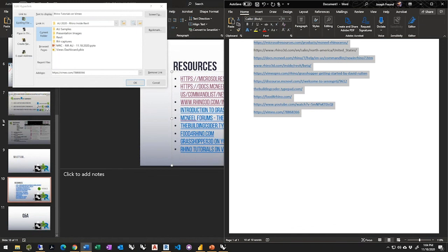There have been a couple that talk about the BIM 360. So BIM 360 is a hosting platform. If you open your BIM 360 model inside the Revit environment, you can continue working with Grasshopper Rhino.Inside.Revit with it. As far as Rhino.Inside.Revit cares, it's just a Revit document, and you can then synchronize it with BIM 360. Whereas you can put and use the Rhino.Inside.Revit capabilities over the Autodesk Forge using the Forge Design API and stuff like that. That needs to be tested and figured out in the future to see if we can install this on the cloud and sort of use these features to batch process Revit models.